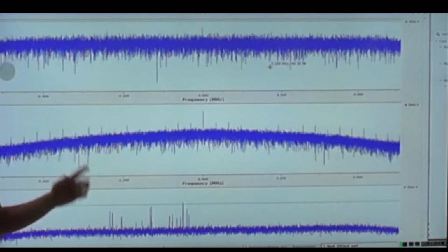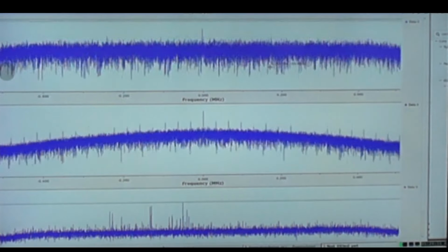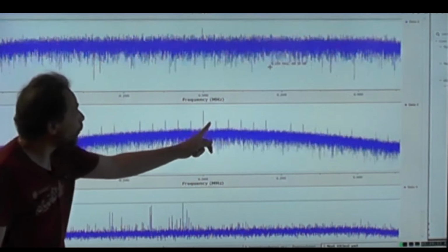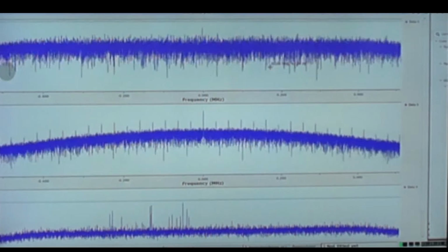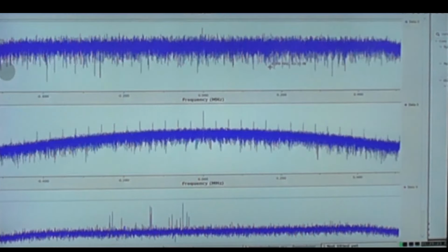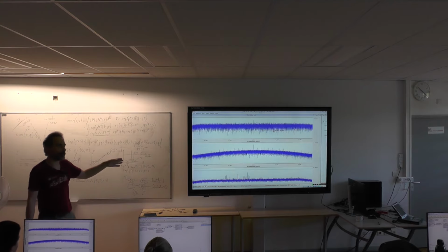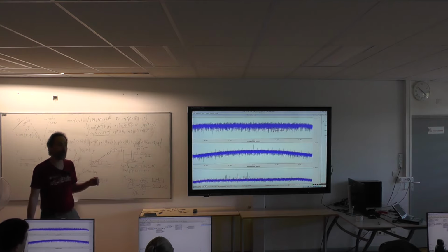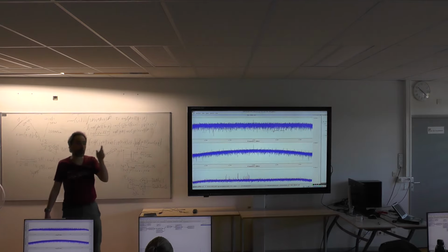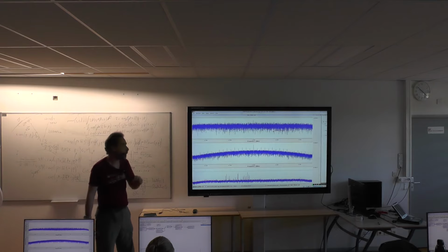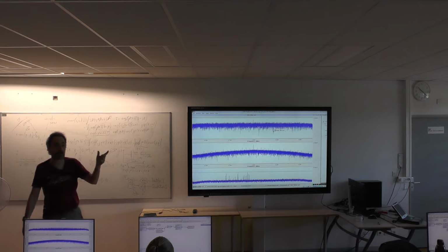We have the Doppler shift of each satellite, but we lost the information which satellite it is. And what you see here are the cross correlations at the repetition rate of the GPS signal. Now you might ask, but in the same band there's a Galileo signal as well. Why don't I see the repetition rate of Galileo? Well, because GPS legacy L1 is a 1 millisecond long code, and Galileo is 4 times longer, 4 milliseconds.